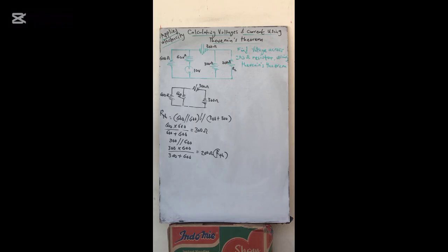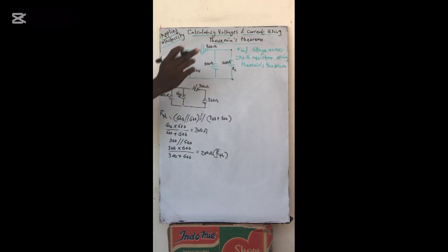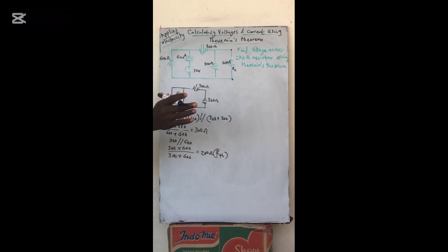Now we've gotten the Thevenin resistance. That's the first part. We're also going to get the Thevenin voltage, VTH. How do we do that? We are going to put back that source that we short circuited, this 10V, and we are going to leave this place open circuited. What is open circuited? This means that there will just be 2 points here. This one will be eliminated, as if we never had it before. So any current that flows through this place downward is not counted, and it's not counted as any resistance functioning. You only face the functioning resistances.